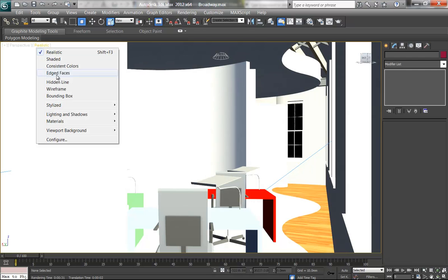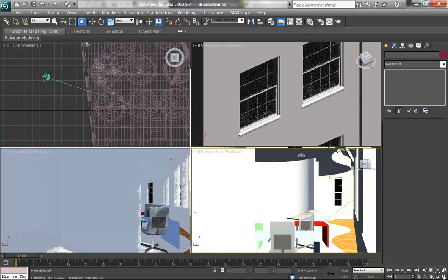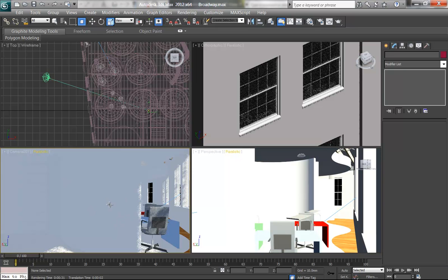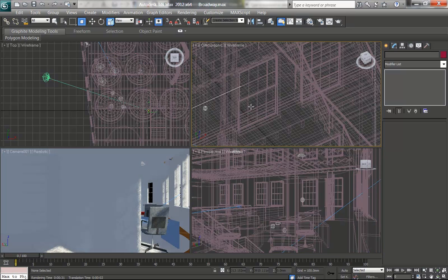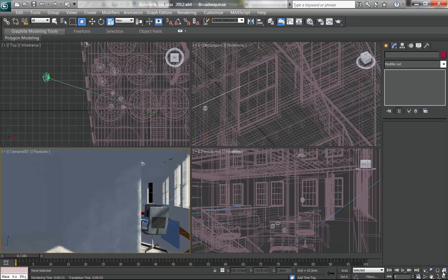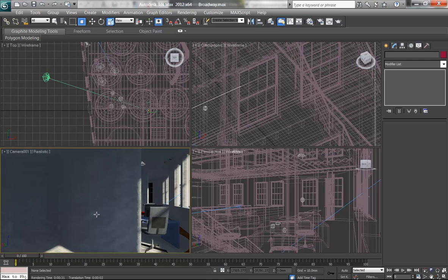It's good when it works, and I think it is something you will need to do at some stage. This one's the one I'm going to work in anyway, so I'll just use that. So here I'm going to set that to wireframe, and this one as well, because when you've got several shaded views, it really will start to overwhelm your hardware. But anyhow, I've got the camera view working, and that's the one I want.